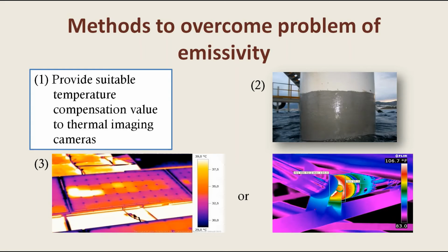An alternative to this method is to make a comparison of thermal profile patterns between objects of similar emissivity operating under similar conditions. This way, we measure the temperature of each individual object, thereby identifying the faulty object in an equipment or manufacturing plant. Hence, timely maintenance can be done before the equipment fails to operate and causes more damage.